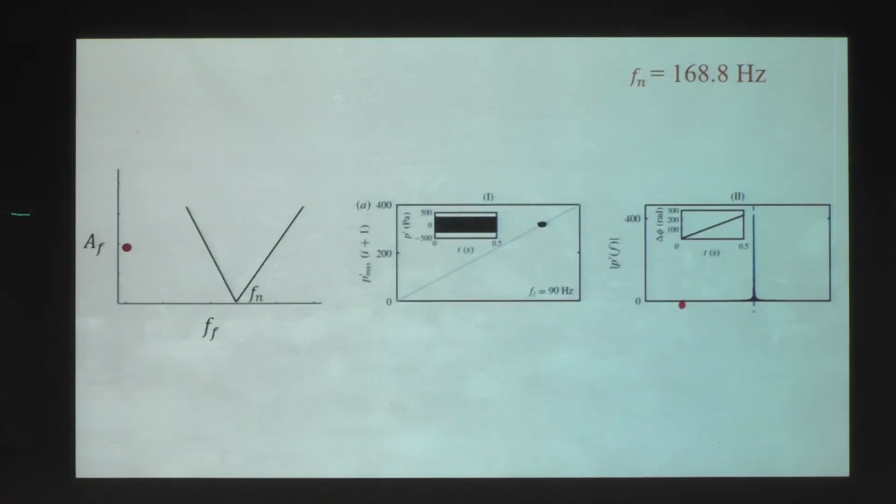When our frequency is far from the natural frequency, here is our forcing frequency, and you can see that the pressure oscillation, this is the response oscillation, is almost periodic. So basically the forcing doesn't affect the self-sustained oscillation. That is also confirmed by this cluster of points in the first return map. And in this plot you can see the amplitude spectrum, with one clear peak, and this is the phase difference, the most important plot here, between forcing and the self-sustained oscillation.